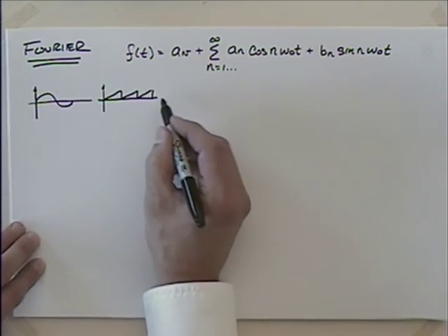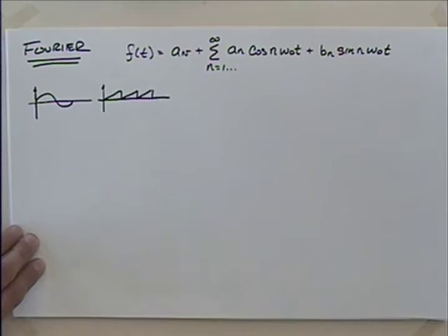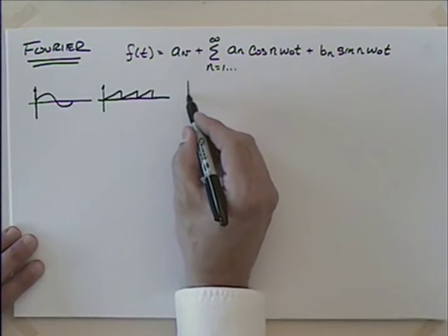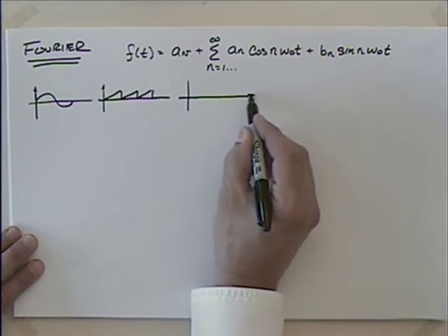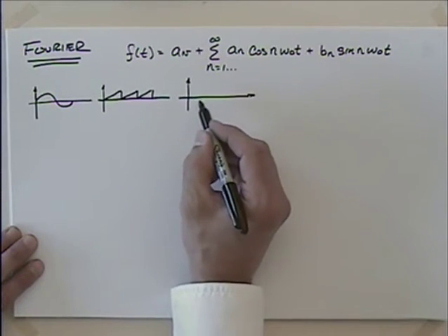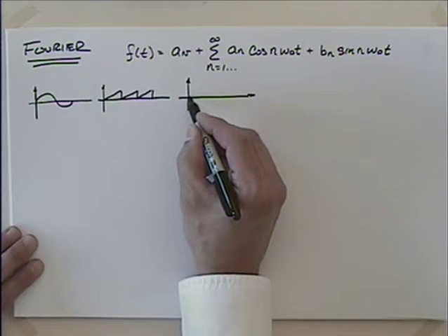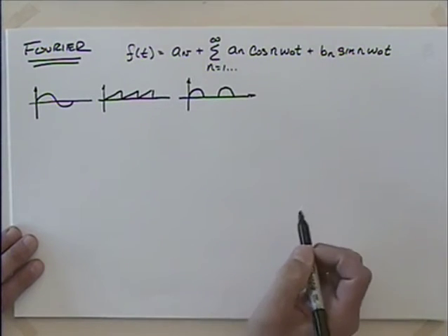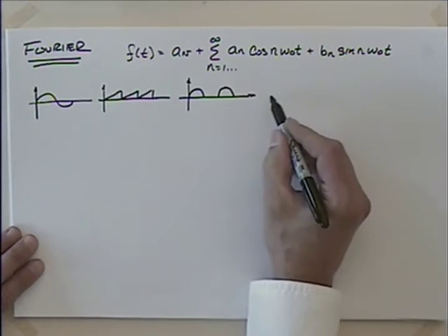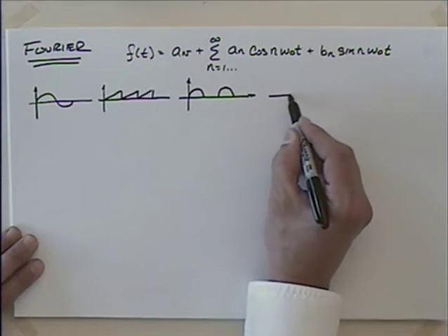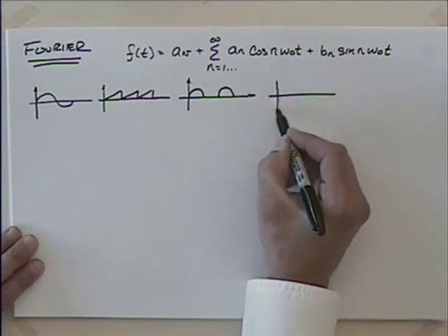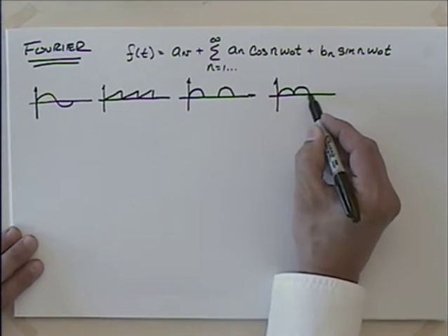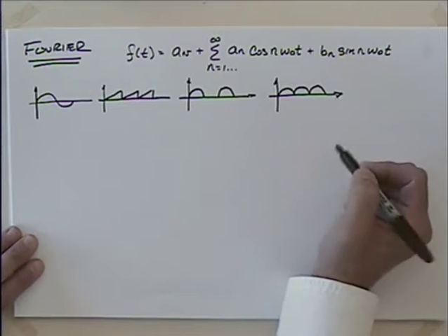Ones that come up all the time, and we're going to tackle more eventually, is a half rectified wave. Let's say you're doing some power supply work and you want a really cheap power supply. You can take a sine wave and use one diode and you get a half rectified wave that looks like that. You might use 4 diodes, a diode bridge, and you get a better wave out of it. It will flip the bottom up, so you get a fully rectified wave like that.